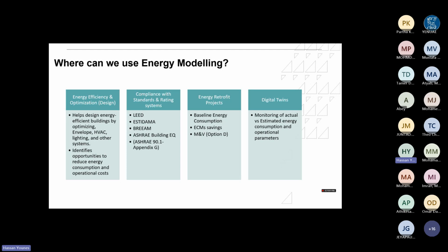So in order to answer these questions, then we could say, well, instead of the 0.57 U value, if I use a 0.4, now there's obviously an increase of cost in terms of the installation, but there will be a decrease of cost because now I have smaller equipment on air conditioning, and I have lower energy consumption. And let's see what is that payback period. So the energy modeling, again, will not give us all the answer, will give us the part of the energy. It's not going to give us the cost of the increased installation or the cost of the reduced capacity of the air conditioning units. That's something we need to check on our own, but it will tell us what is the energy consumption, help us make that decision.